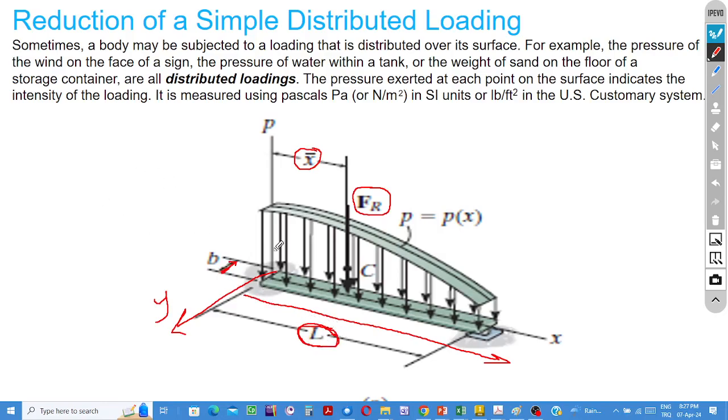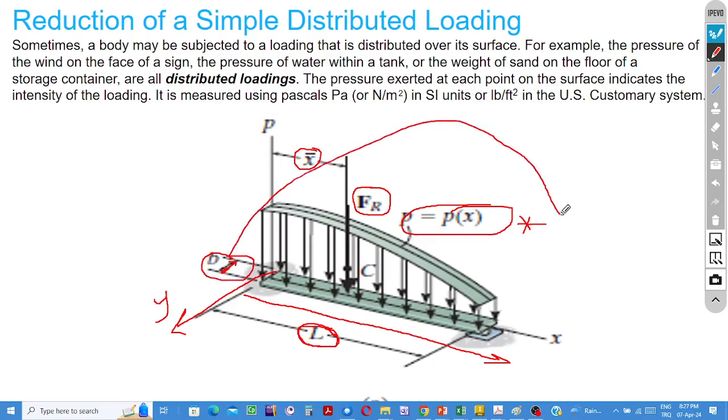In such a case, if the load is a function of only one coordinate value and the other direction is uniform, it is common practice to multiply the surface pressure, the given load function, by the dimension of the contact surface in the direction where the distribution is uniform or can be very accurately assumed as uniform.